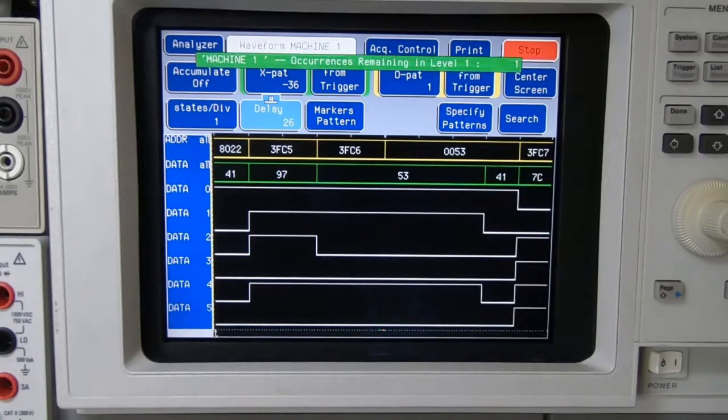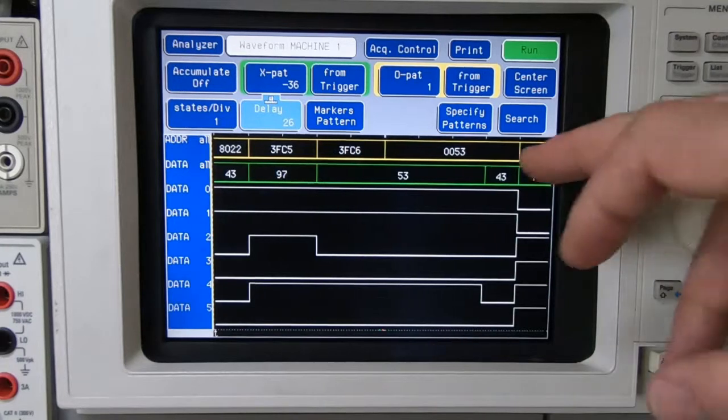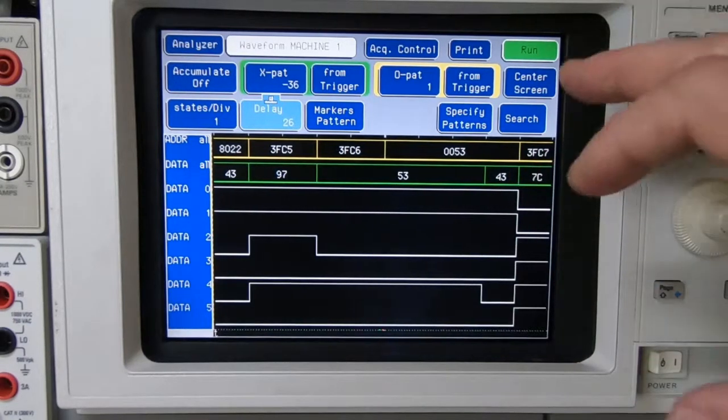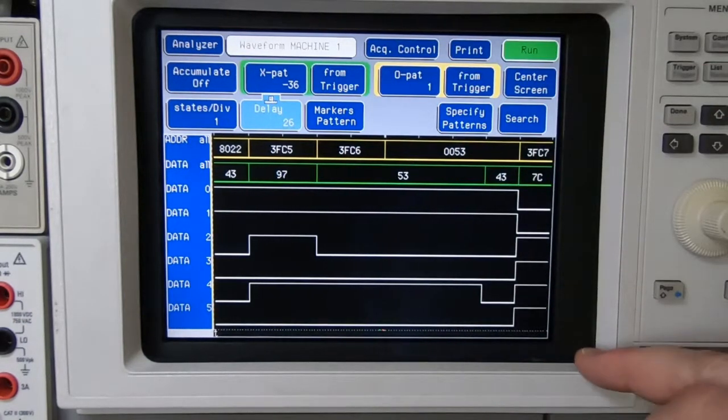If I just now reset the trigger and press the key on the tape reader to read the next data byte, you can now see we have an address, data value of 43. So in other words, what this is now doing in the IRQ is we are just reading the value from the PIA that takes the data from the tape reader. That's all the IRQ actually does.